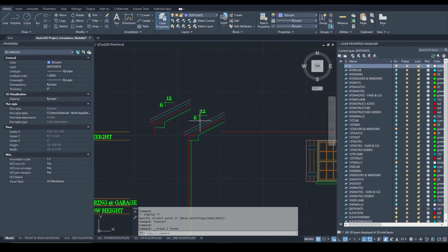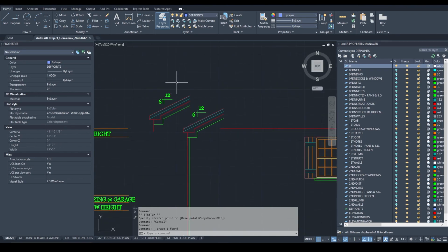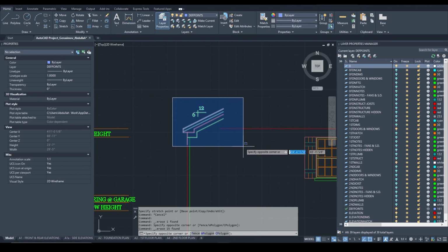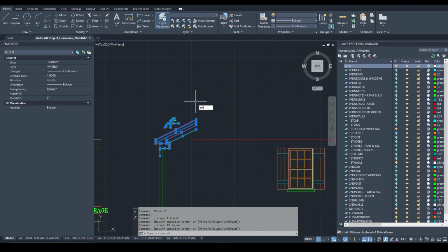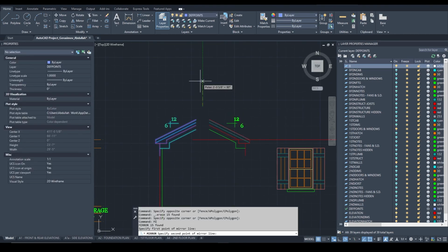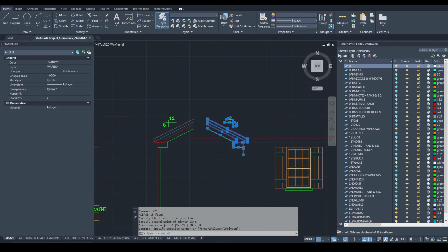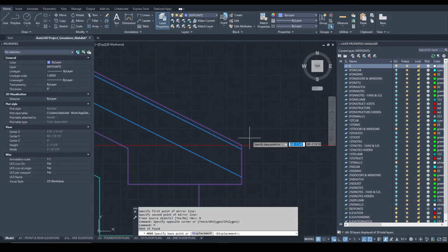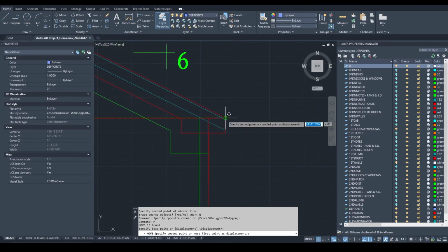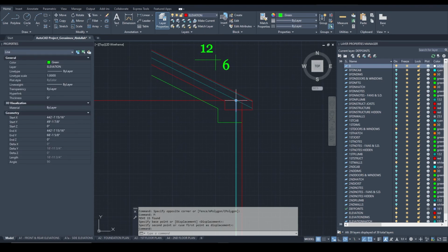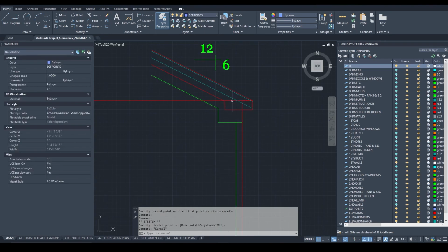Now the same thing is going to occur on the right side of our building as well. The same slope, the same types of lines. These ones we can remove since those have been only for reference. Let's select the same thing we have copied and copy it to the right side. Or what I like doing is mirroring it first so that I don't have to worry about redrawing it. I press MI and I mirror it, and I copy the right corner and align it with the right side of the building outline or overhang, and repeat the same process of trimming the extra lines.